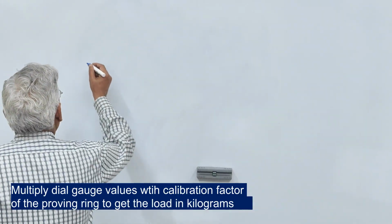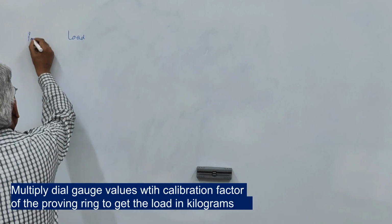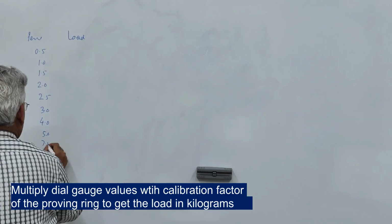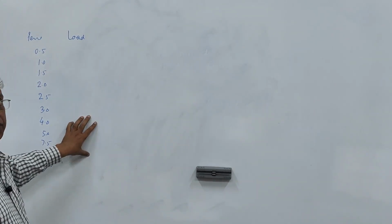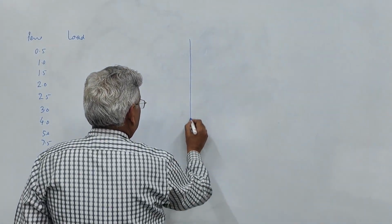Now you have load for a penetration of 0.5, 1, 7.5, 10 and 12.5. Corresponding to these penetrations, which are in millimeter, you have load values. Now you make a plot on simple graph paper.